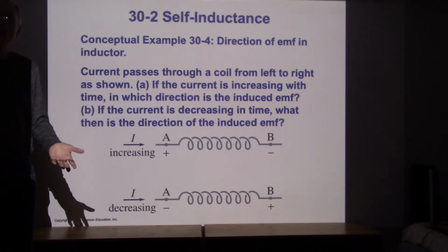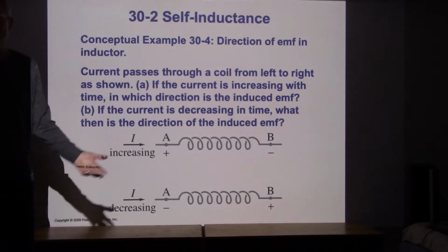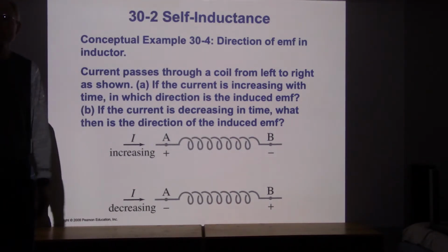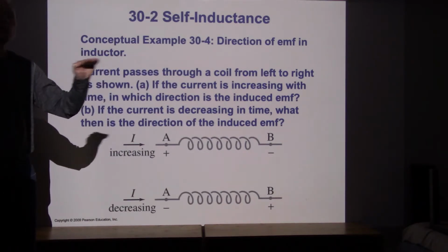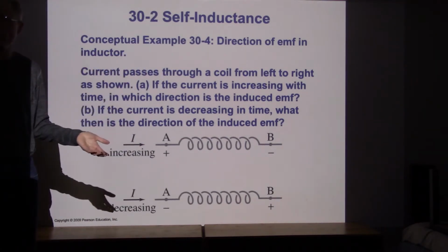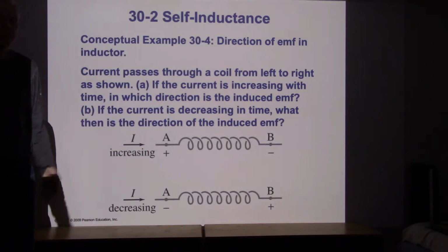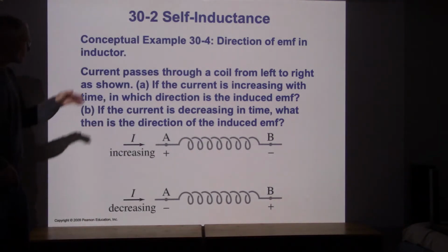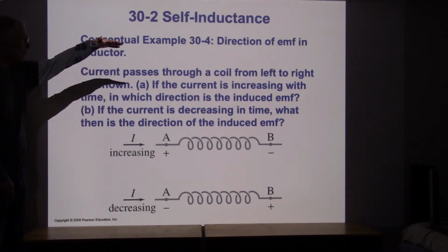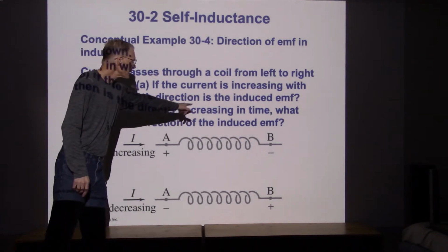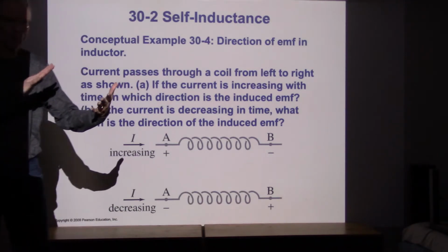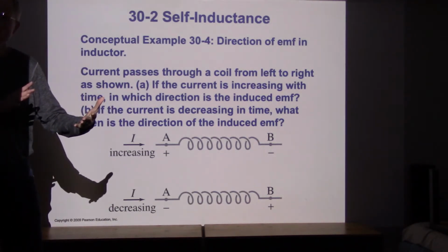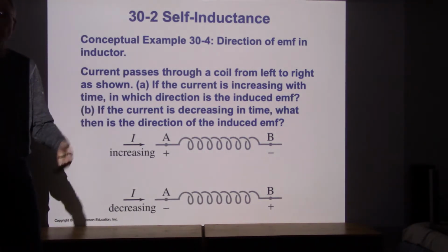When are inductors happy? It's when the current's constant, right? If the current's just constant sailing through, there's no effect. You can ignore the presence of the inductor if the current's constant. But if the current is ramping up, then they will create a voltage drop in that section of the circuit, and that has an effect to moderate the change.